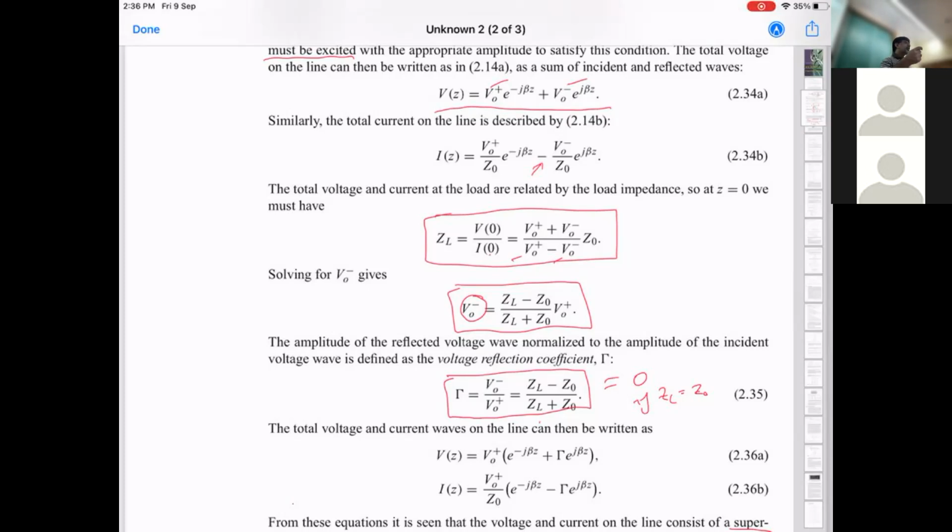Because every time you connect two cables, so again, this is something in the conventional sense, if you're doing a breadboard circuit and you do not have a long enough wire to go from one end to the other end, you just take two wires, either solder them or just twist them, and that's perfectly fine, right? What could be the problem there? That the two wires might have some contact resistance, but that's going to be insignificant compared to the resistance of the rest of the circuit, so you don't really worry about it.